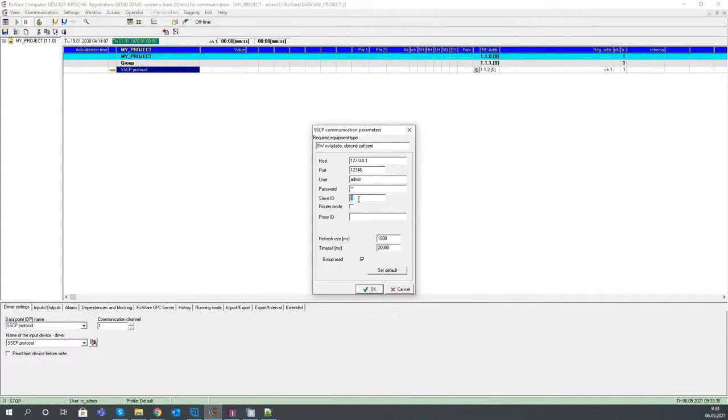If you know the Modbus topology, like Modbus RTU and Modbus TCP routing, that's a similar issue. All of your, for example, energy meters have different addresses from 1 to 250, but the Modbus router only has a single IP address, and through this address and the slave ID, you access the individual meters. In this very same way, you would access your PLCs, which are behind a single Ethernet connected PLC on an RS485 serial line. To make the long story short, normally if we only have a single PLC on an IP address, the slave ID will be 1. Okay, the proxy ID, this is not an issue now.